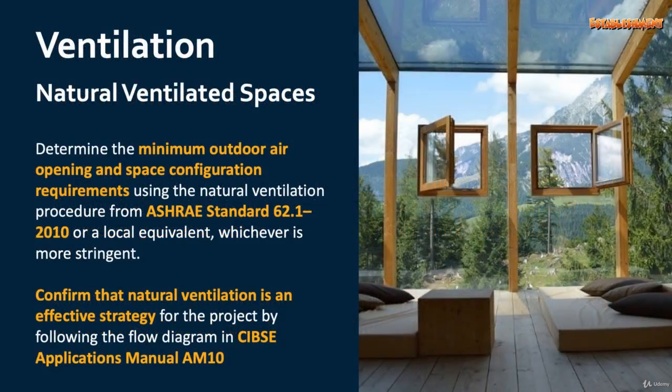In case of naturally ventilated spaces, determine the minimum outdoor air opening and space configuration requirement using the natural ventilation procedure of ASHRAE standard 62.1 2010, again, or local equivalent, whichever is more stringent, and confirm that natural ventilation is an effective strategy for the project by following the flow diagram in the CIBSE application manual AM10.